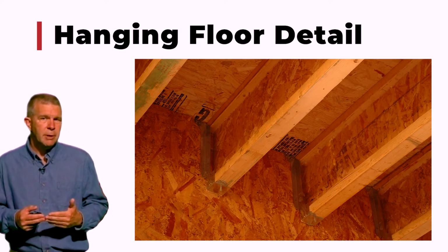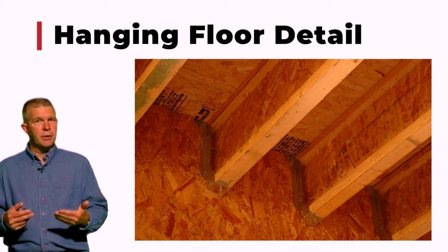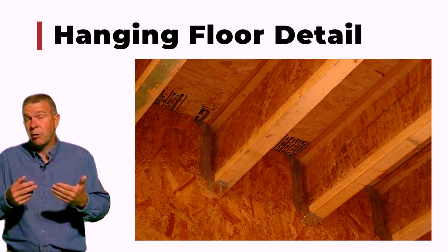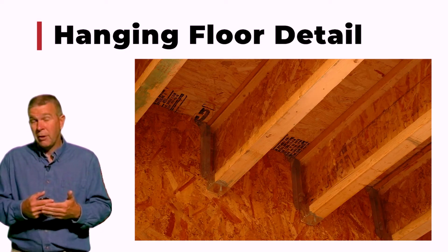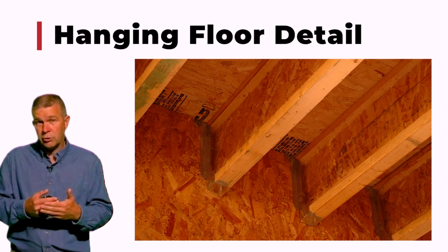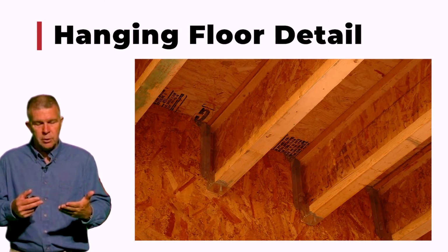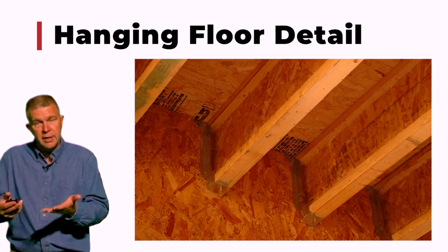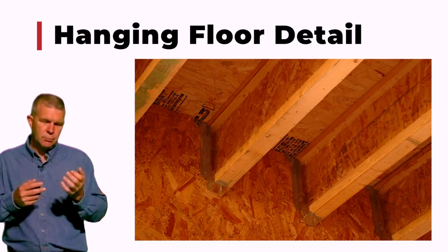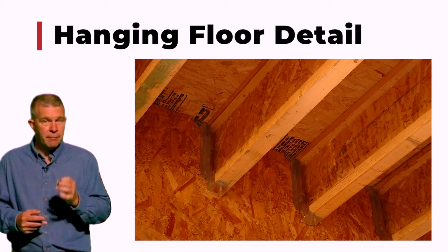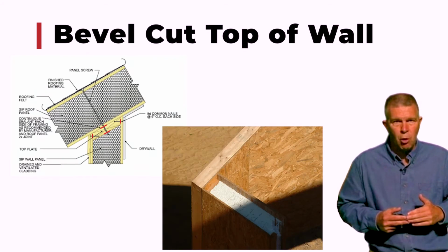The thing that you need to be aware of is when you do a hanging floor system, in some cases you have concerns about moving your electrical from one system to the other because you don't have the advantage of dealing with that floor system to work inside of. But one of the big advantages that the hanging floor system also gives you, it increases the diaphragm capacity of that connection between the floor sheathing and the wall itself. It's a great system. It goes up just as quickly as a platform frame system, and from an energy standpoint, it can't be beat. Let's continue working our way up this wall panel.